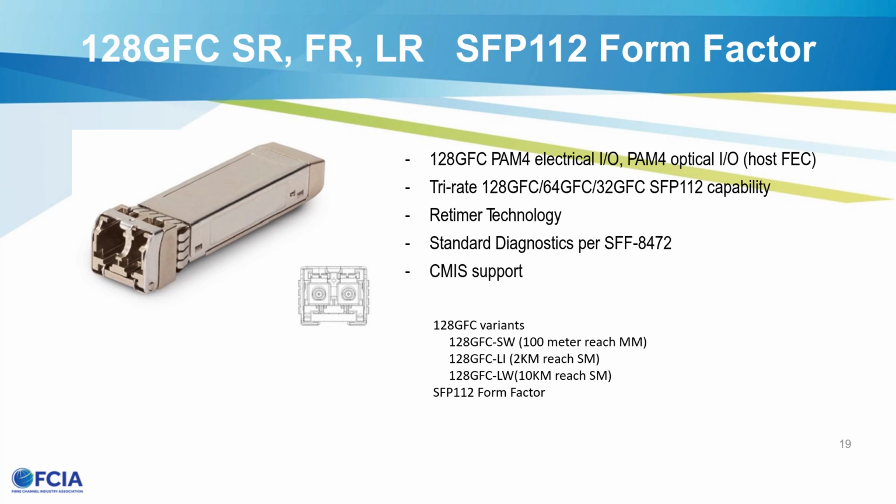I think 128 GFC has SR, medium range, long range modules that are optical and electrical. They're in an SFP112 form factor. There's an SFP56 form factor that was used for 64 GFC technology. And they're standards based.